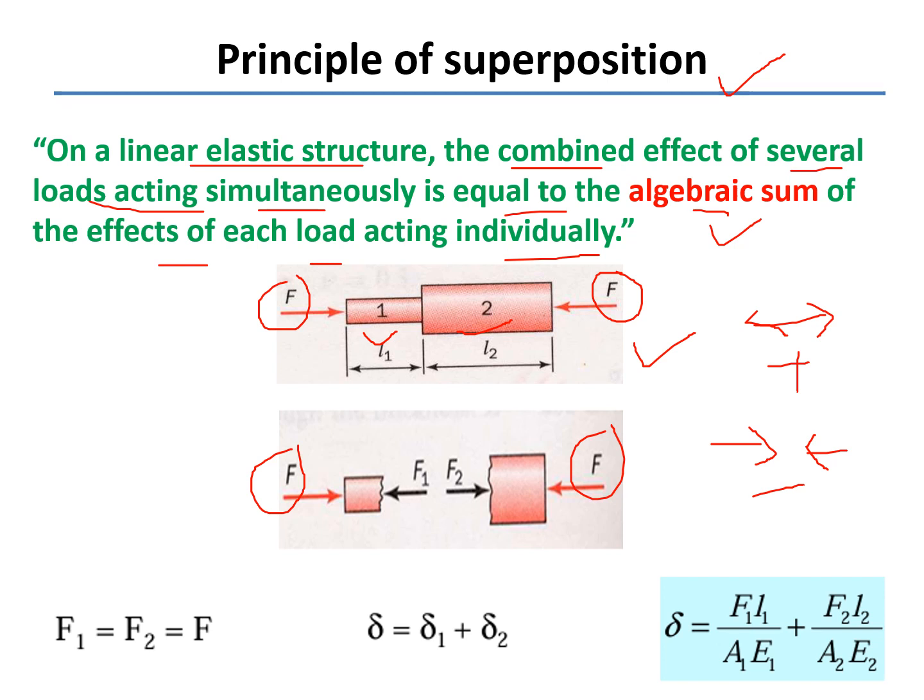So definitely we have a force on its right face in the leftward direction. And if this body is under equilibrium, so definitely this F1 is equal to F. In the same manner, this section is also under equilibrium. We have a force F on its right face towards left. So definitely we have a force on its left face towards the rightward direction, and definitely this F2 is equal to F. So F1 is equal to F2, and that is equal to F.